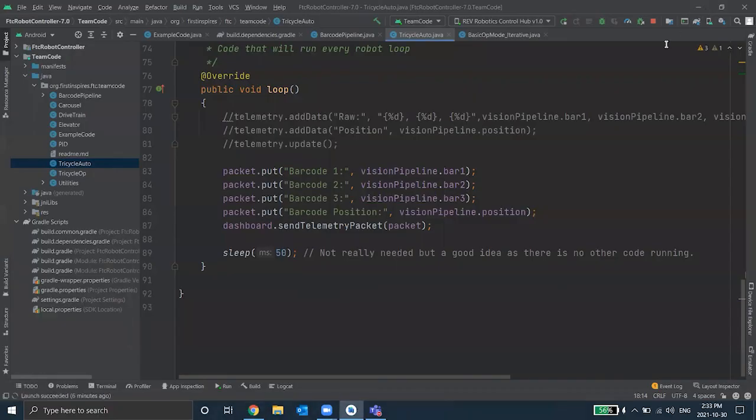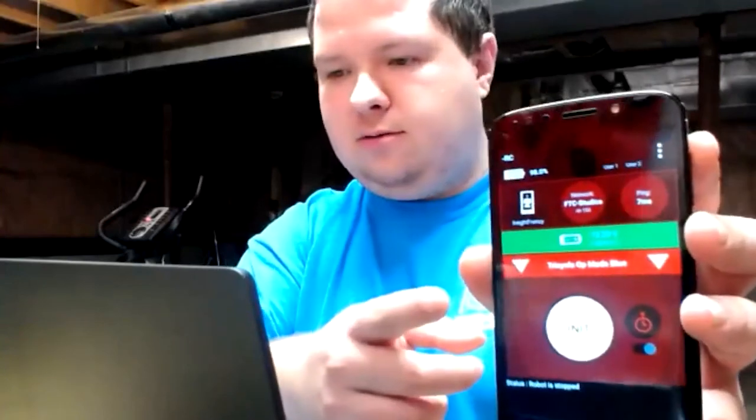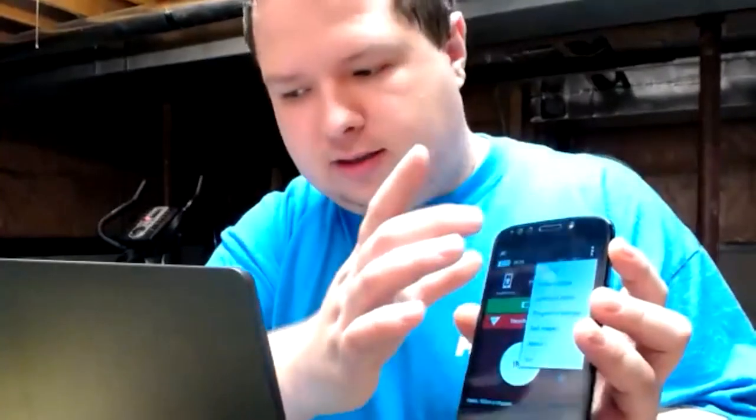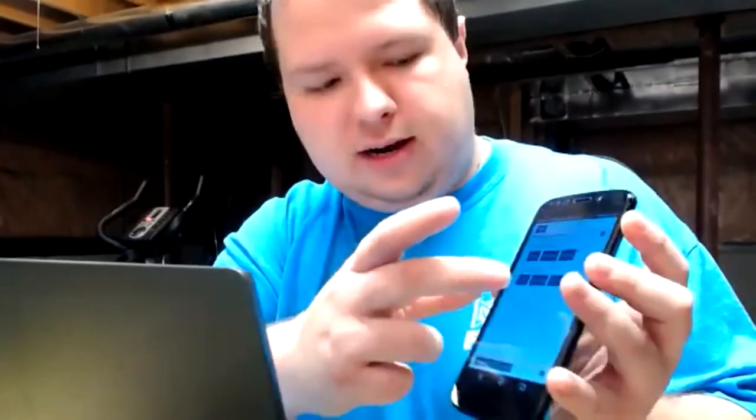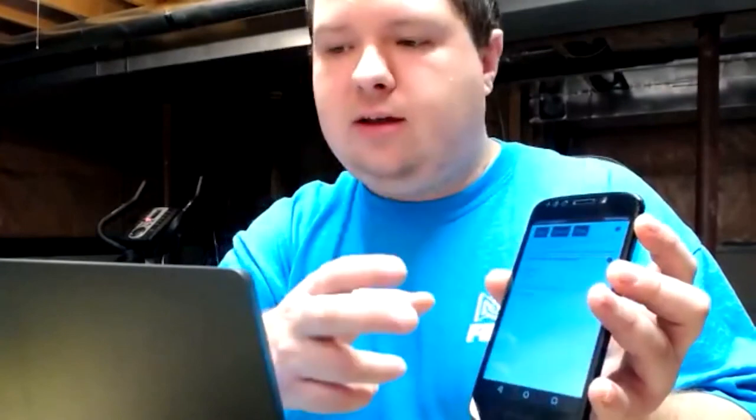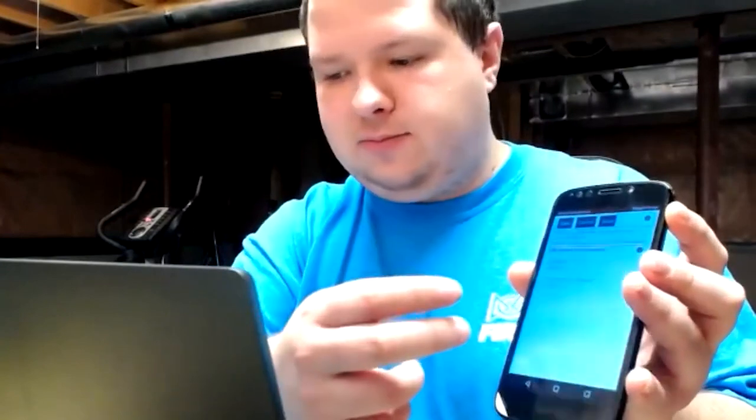So someone asked about configuring the Tetrix Tornado motor with the controller. What you would do is, here I can show you. I'm just going to stop sharing my screen so you can see a bit better on the screen. So inside your phone, you click on the 3 dots, go to Configure Robot. Inside one of your configurations, you're going to hit Edit. If you don't have a configuration, just click Create New.